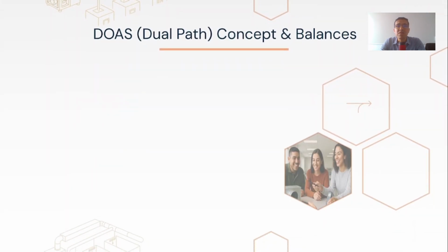So, continuing with this, let's now explore a more advanced system architecture that fundamentally changes how we handle ventilation and cooling, the dedicated outdoor air system, or DOAS. This strategy is all about splitting the job to improve efficiency. DOAS is a clever system that decouples the ventilation stream from the recirculation stream. The dedicated outdoor air coil handles the ventilation air, cooling it to a low temperature to remove moisture and satisfy the space's latent requirements. Meanwhile, a separate return air coil provides mostly sensible cooling to the recirculated air.